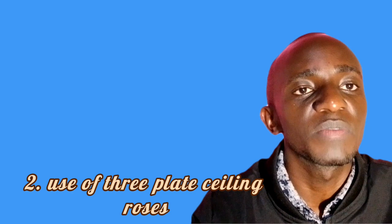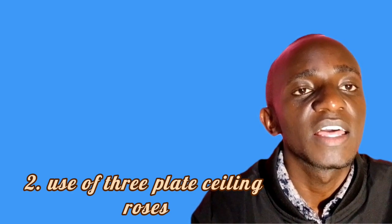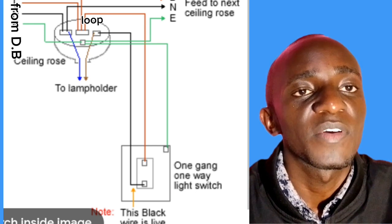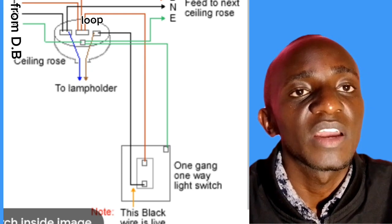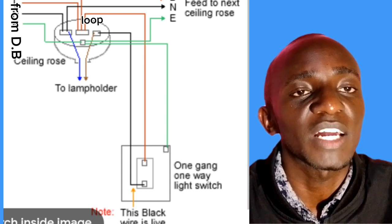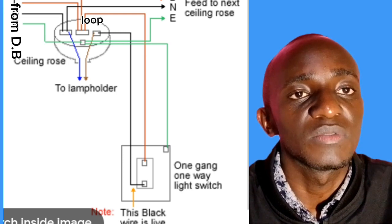Okay, the second method of connection of lighting circuits is by use of 3-plate ceiling roses. A 3-plate ceiling rose has 3 plates, or just 3 terminal blocks, and an additional block for earth. We will look at IEE regulation, and one of the regulations is that all ceiling roses should have an earth terminal, and those earth terminals should be connected with the earth conductor. And we are going to look at the reasons as we continue.